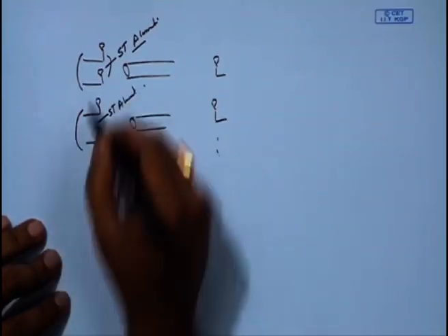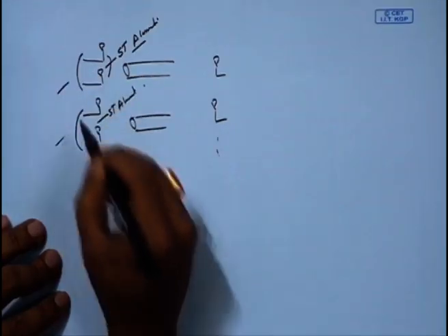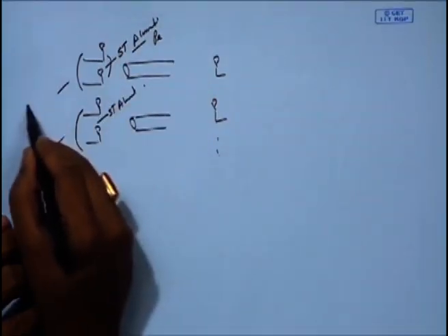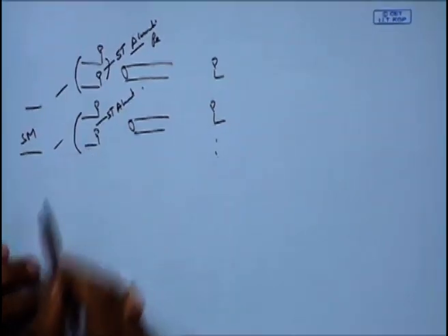In this way we achieve 2 orders of diversity at the transmitter in each of the links, and we have 2 links. So, we would improve the probability of error here, and we would achieve a certain amount of spatial multiplexing. So, this is one possible way of doing it.